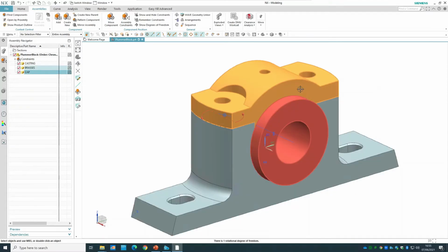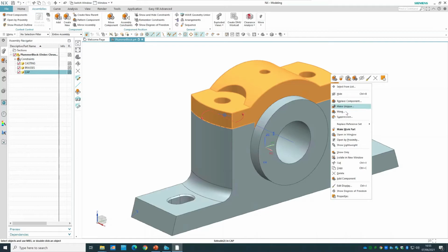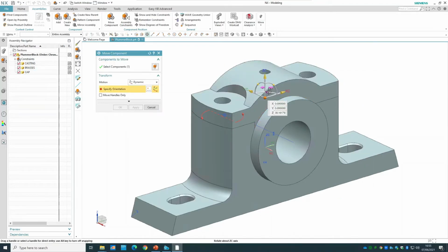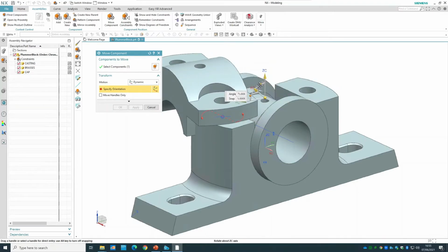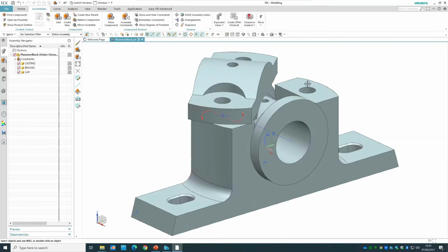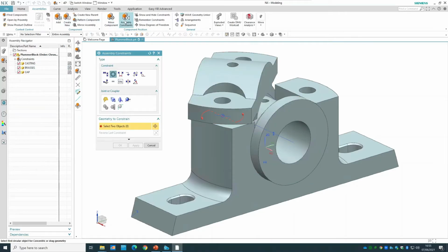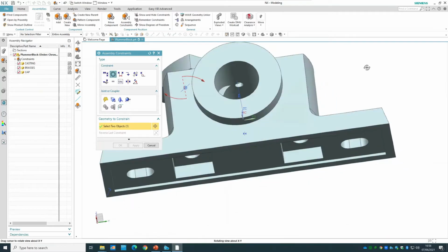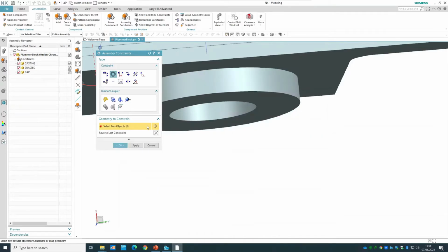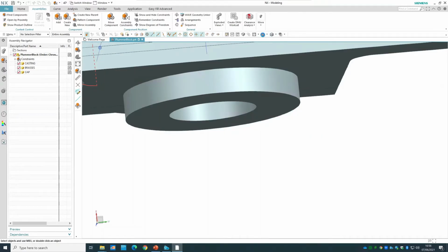What you will see here, it's their assembly and you think it's right, but let's double check the degree of freedom. And what you see is it still rotates. So what does it mean? It means that if I go to the move, I would be able to get that rotation, which is not what I'm looking for. So again, what I can do, I can use infer between those two. I can use touch between these two, or I can use one more concentric. Let's go and use one more concentric between this one and what I have there. And click OK.